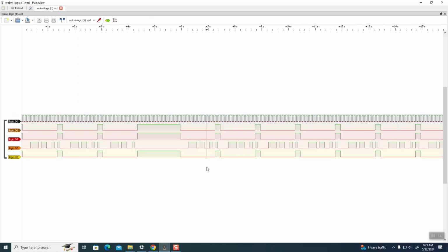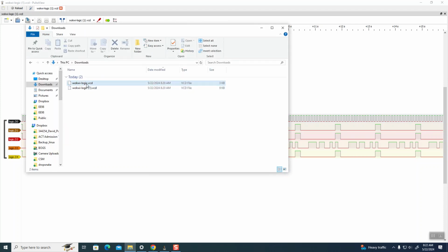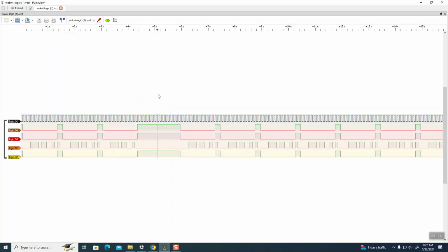Now, if all of a sudden it's taking forever to draw your circuit's response, you probably didn't downsample right, and it might crash. It'll keep doing that, even if you exit the program and come back in, it'll remember the last thing you did, and it'll keep crashing. So you have to go back and delete the original file, or actually just rename it. Then it'll come back normally.